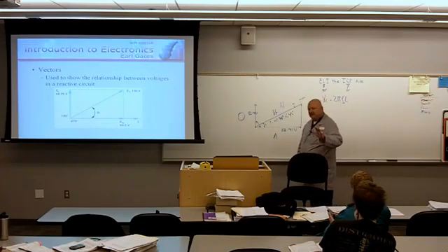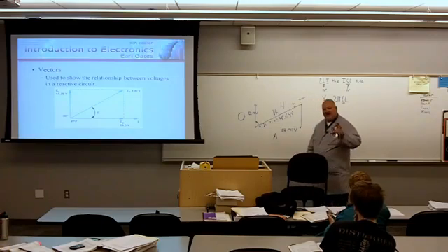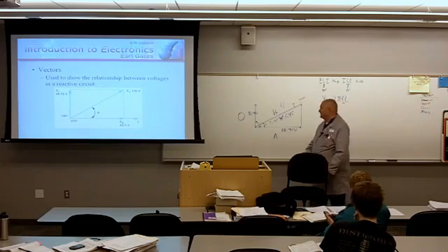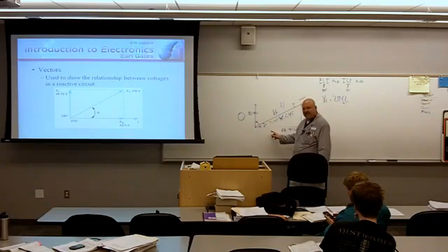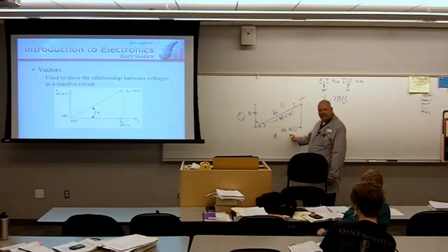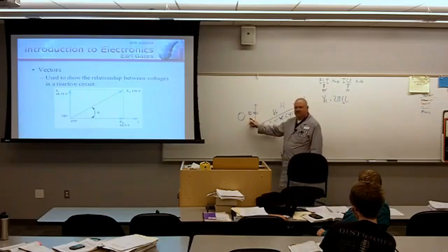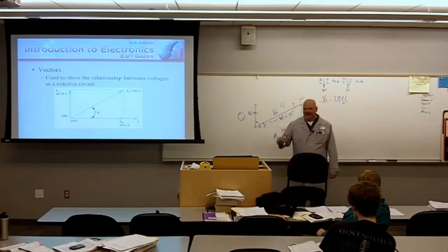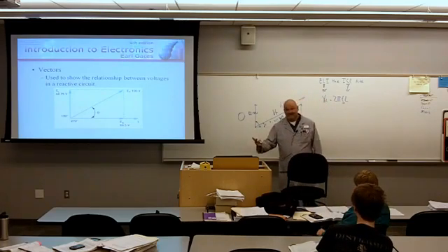On professional examinations, they will say in a series AC circuit that contains a resistor and an inductor, you have 10 volts voltage drop across your resistor. You have 10 volts voltage drop across your inductor. What is total voltage? Answer A will be 20. And you'd be surprised the number of people filling it in. Answer A. Because 10 plus 10 is 20.